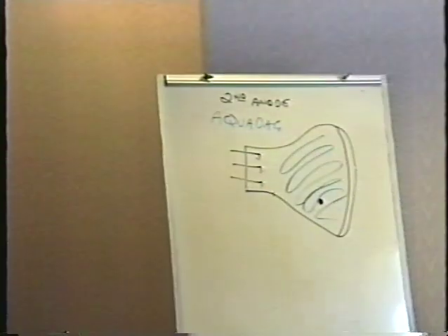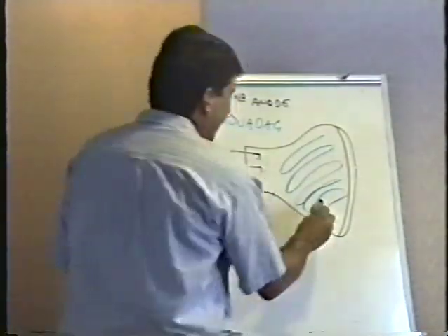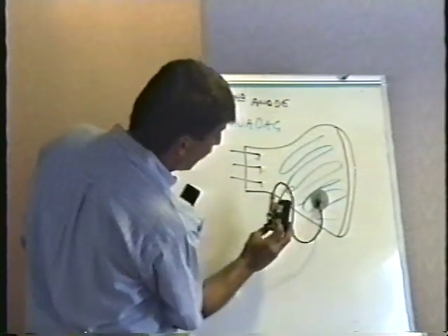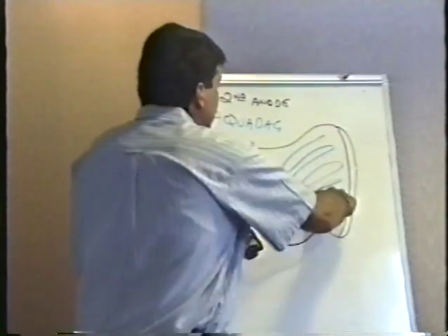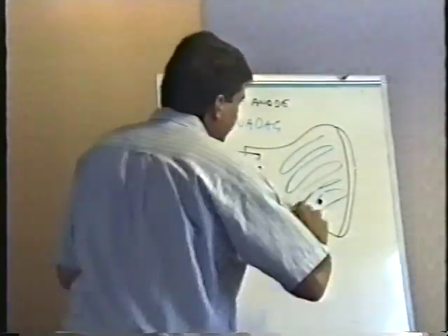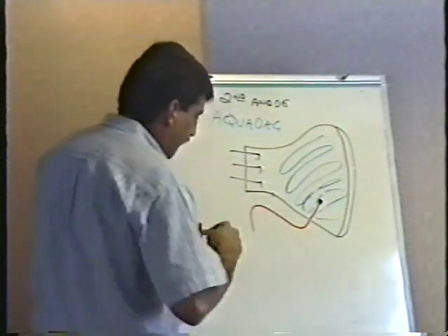And this guy is connected to the high voltage unit in the monitor. Let's find my high voltage unit here. The second anode is connected to the high voltage unit in the monitor, and there's the high voltage unit right there. This is a bad high voltage unit. I'll show you this up close later on. You can see it's like wiped out. It's always connected through this very heavily insulated red wire and goes into the high voltage unit.